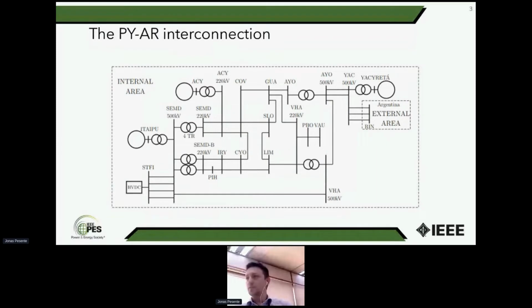For the safe operation of this interconnected system, a special protection scheme was developed to assure the system will be stable after large disturbances, and also 2 out-of-step protection functions were enabled to perform the special protection scheme backup, and this protection needed to be tested.